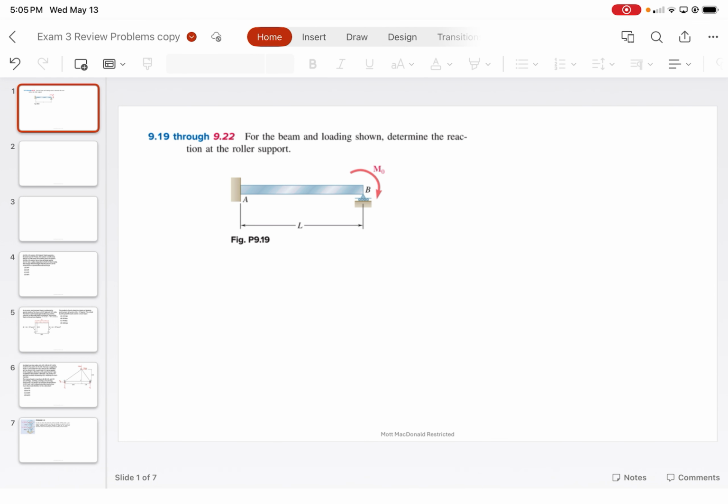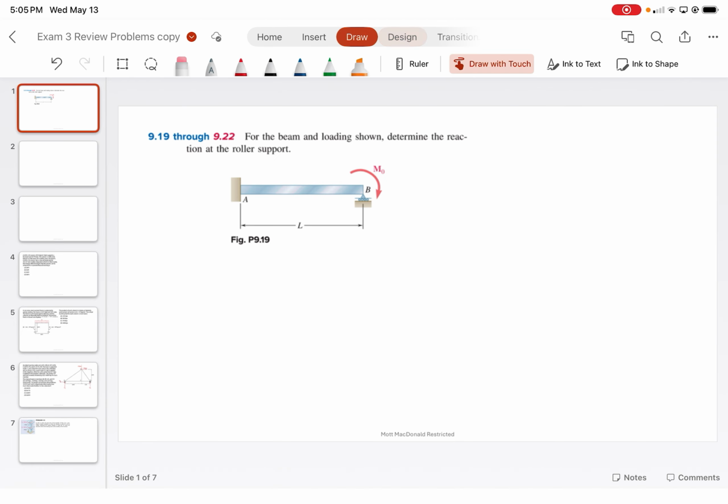How do we solve statically indeterminate structures? There's a few ways we can really solve this. Remove the redundant. I thought you said, did you say some of the redundant? I might have slurred my own. All right. So remove the redundant and then replace it by its equivalent reaction force.